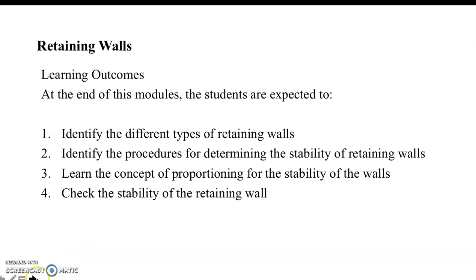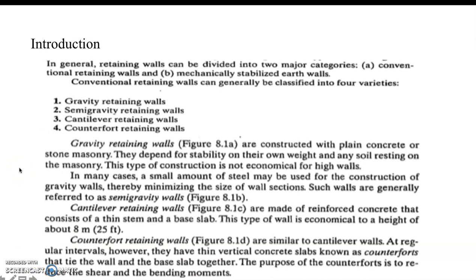So basically, when you talk about retaining walls, those are structures designed to restrain soil to a slope that it would not naturally keep, typically a steep or near vertical slope. So the purpose of a retaining wall is to restrain the movement of the soil, and these are often found in places where extra support is needed, to prevent the earth from moving downhill. So these retaining walls are relatively rigid walls used for supporting soil laterally so that it can be retained at different levels on the two sides.